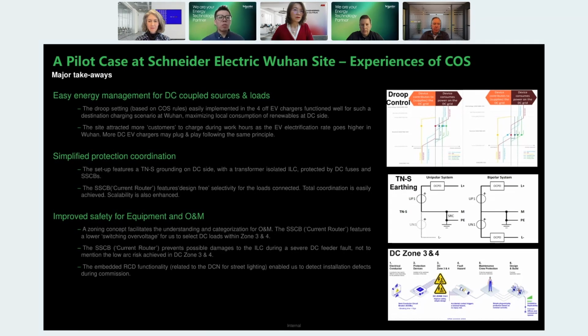With zone 0 and zone 1, they would already know that they really need to take care, because everybody with a power background would know that a 20 kiloamp steady state or peak fault level would be significantly different from something around 100 amp, let's say, within microseconds. So the fault energy level is totally different. The operating team would know it and treat it as a risk assessment by themselves. This is very important for the operating team.